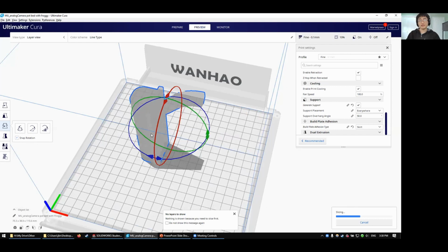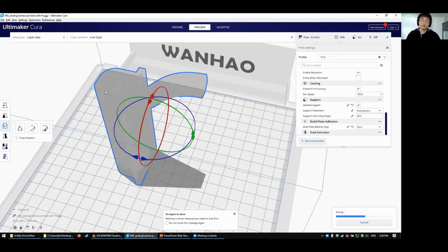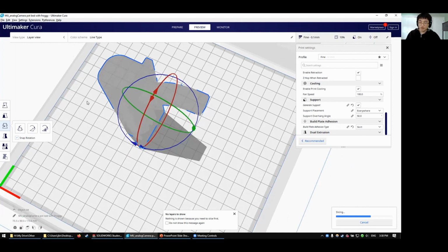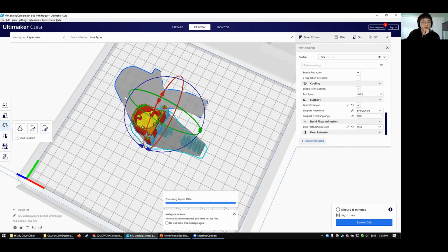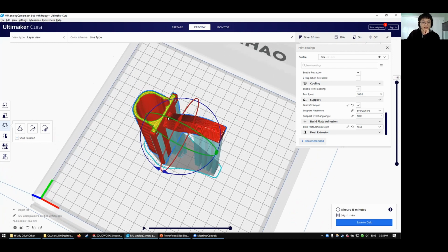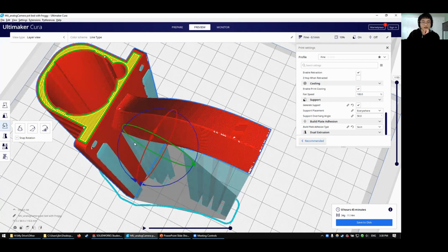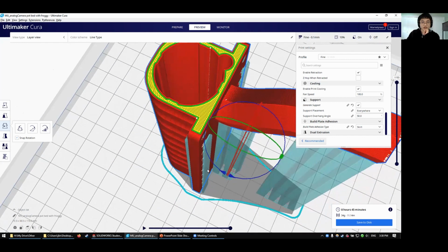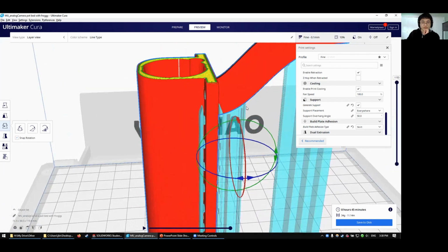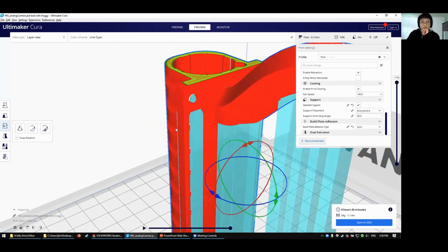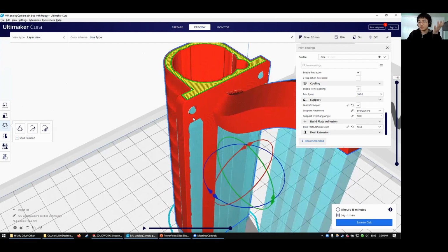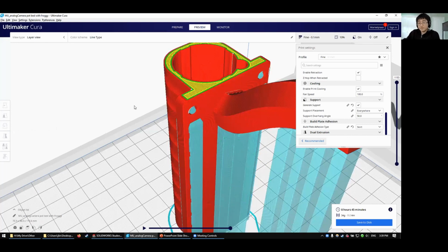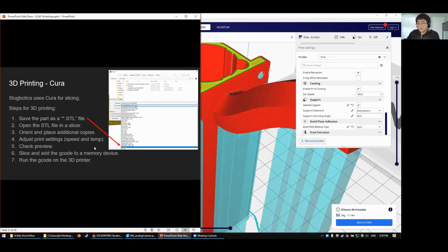If I were to print it flat on its belly on the long side, then there'd be lots of supports inside the cylinder, which would possibly be detrimental, a higher chance of failure maybe, or just take more plastic than was needed. So this way, minimal support. Ignore this red trunk, see if that was ignored. Then you'll see there's very little support needed. Just a little bit along the edges, to make sure the thing doesn't fall over, and make sure you can print the holes as well. Aside from that, just use a knife. Once it's done, just cut out the holes, chop off all the support plastic, and your part's done. So design your parts with how it's going to be printed in mind.